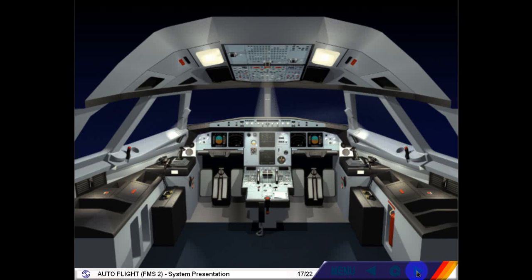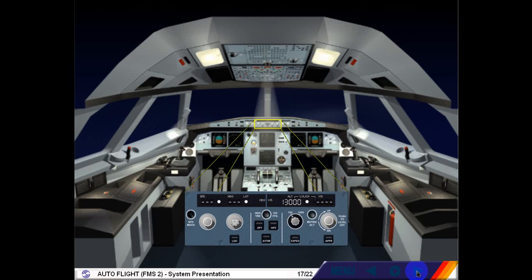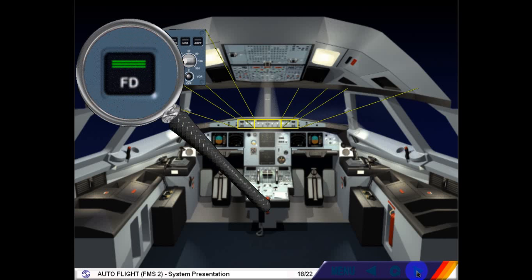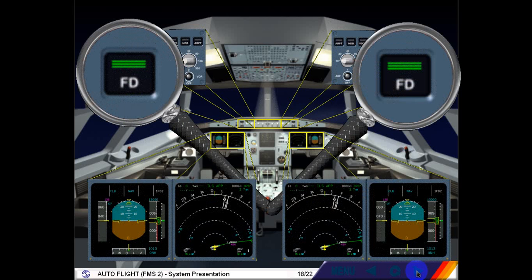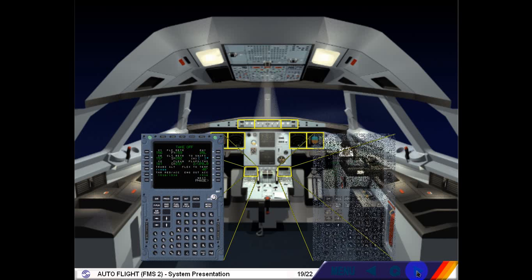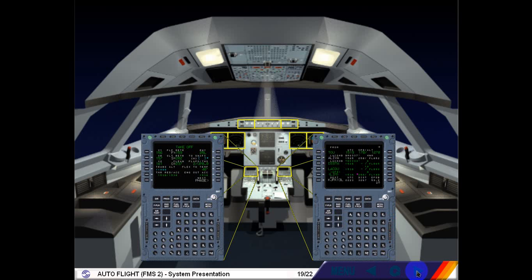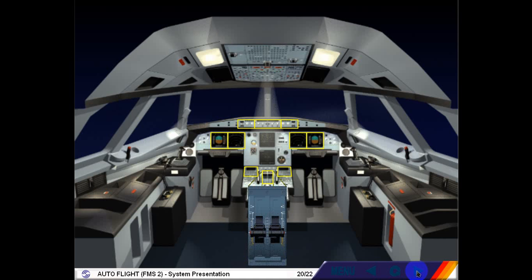The controls and indicators found in the cockpit are: 1 Flight Control Unit, or FCU, 2 Flight Director push-button switches located on the EFIS control panels and the associated EFIS displays, 2 Multipurpose Control and Display Units, MCDU, 2 thrust levers, mainly in interface with autothrust.